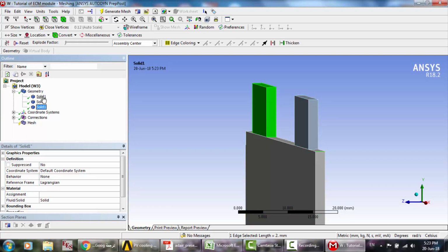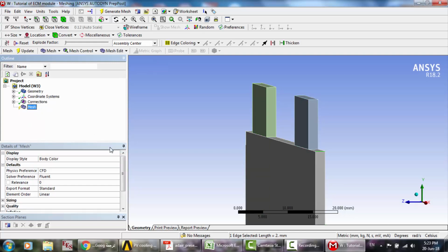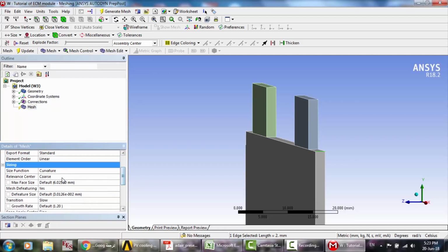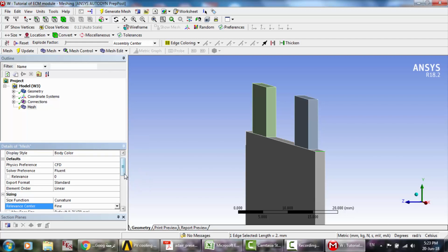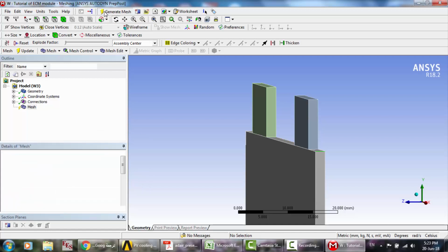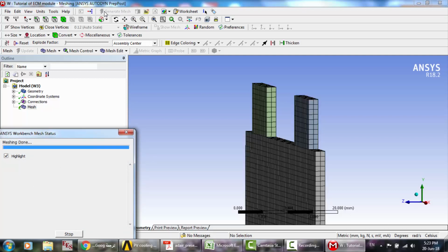Solid, to tell Fluent that we're gonna deal with solids and to be able to define the zones. Here the sizing, I'm gonna make it fine and make it 1 millimeter as an initial guess. Do not use this setting.